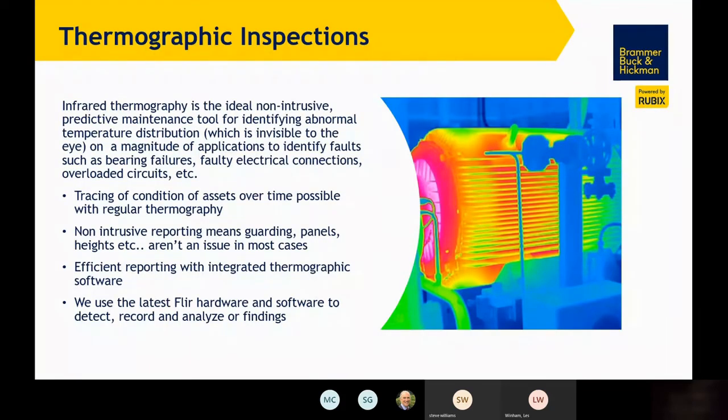So thermography is the inspection of abnormal thermal levels and patterns emitted by an object. As with vibration analysis, done over time, we can trend this information and spot anomalies. We can also use this to do one-off checks, i.e. electrical panel thermography or silo tank level checks, to check for either readings outside of ISO standards or spot readings that differentiate from other sensors.